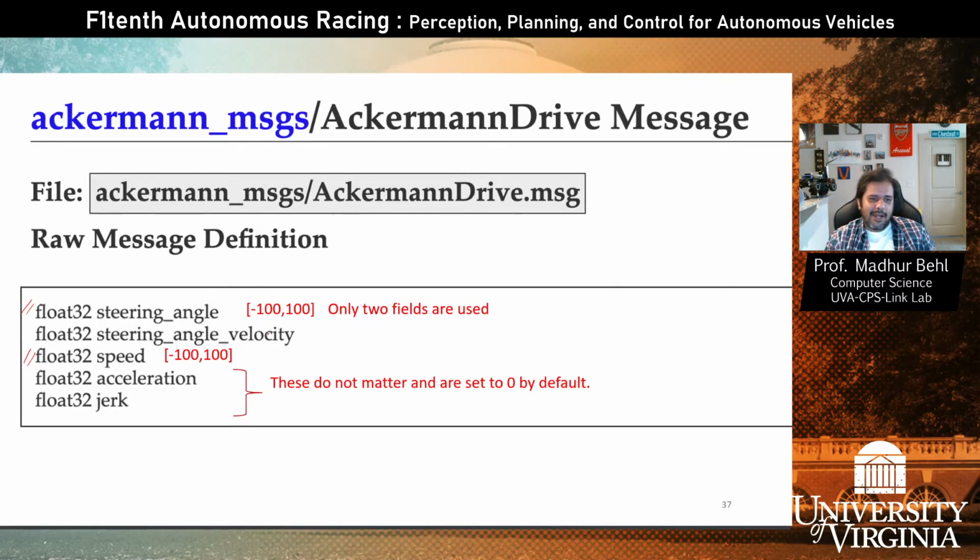And you have to provide values which are between -100 and 100 for both of them. So we are not providing the value of speed in some miles per hour or meters per second, right? This is not what's happening. What is happening is +100 is full throttle, -100 is full brake or reverse. Similarly, +100 for steering is full steering right, -100 is full steering left.